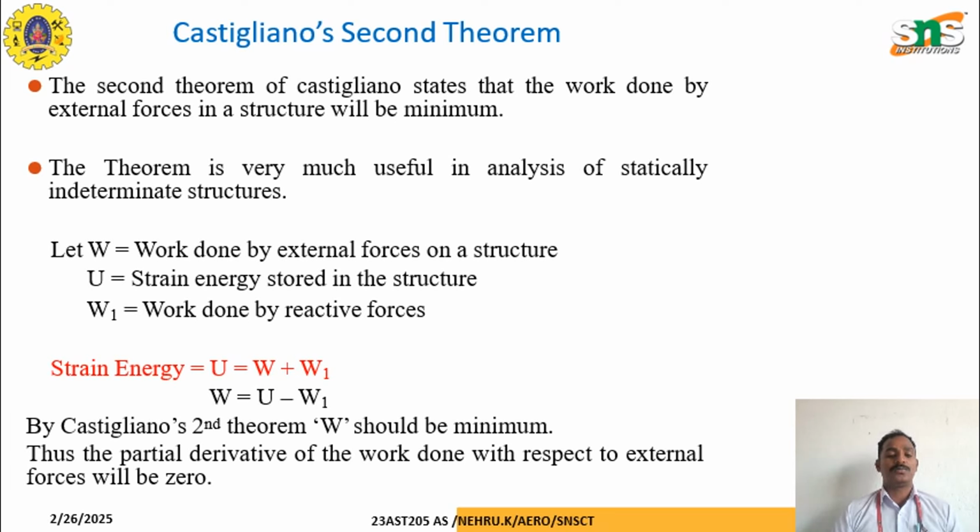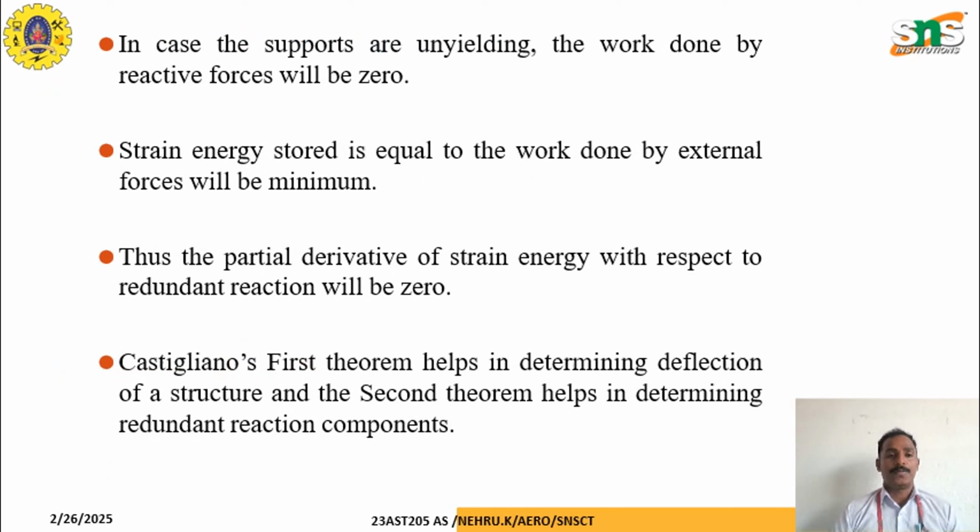By Castigliano's second theorem, the work done should be minimum, so the partial differential of the work done with respect to the external force will be 0. In the case of unyielding supports, the work done by the reactive forces will be 0. The strain energy stored is equal to the work done by the external force, which will be minimum. Thus, the partial differential of the strain energy with respect to the redundant reaction will be 0.